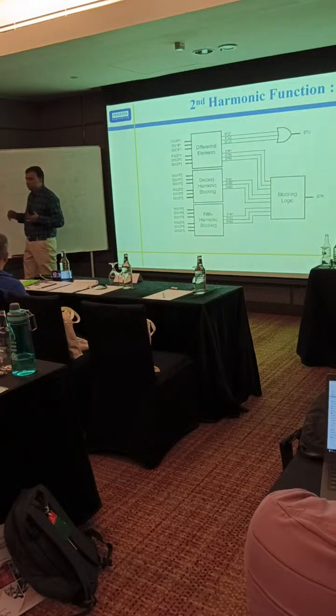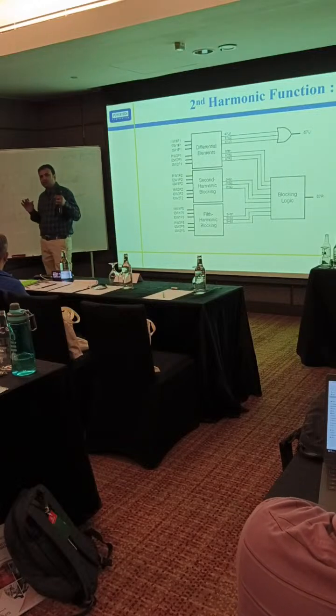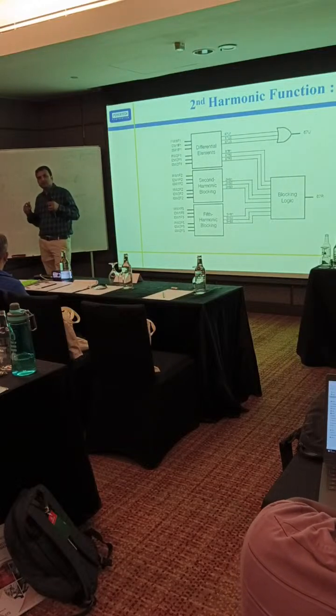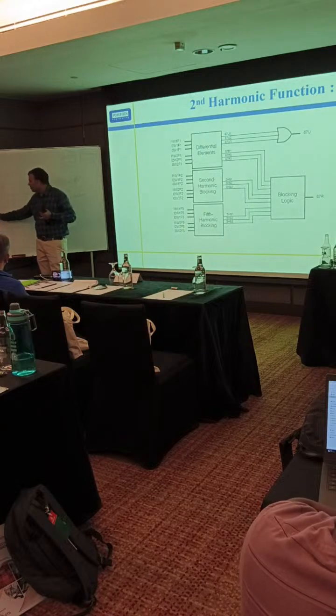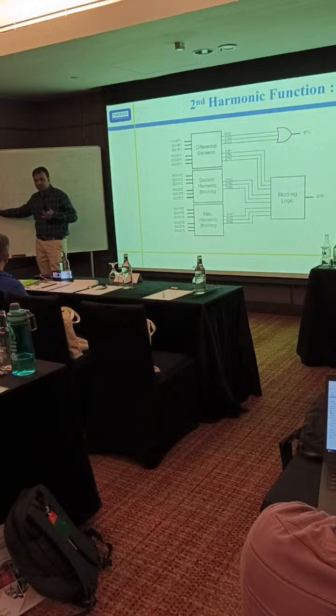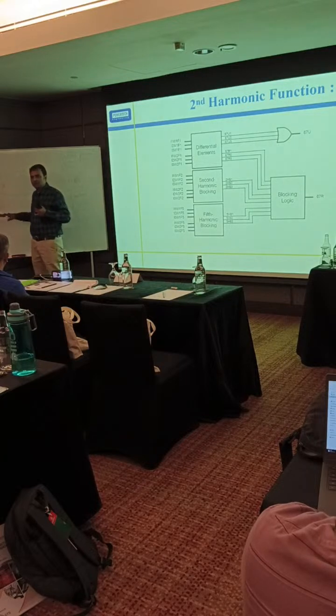So you inject balanced current from both sides. The I bias would be 10 pu or whatever it is, where it is coming. So the relay should not trip, because differential current is not there.